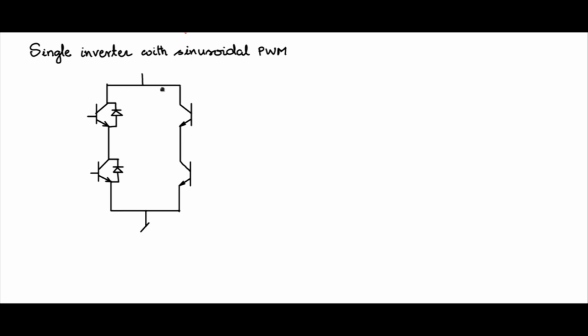So you also put another arm just like this arm. So you have another set of BJTs, a top BJT and a bottom switch, in this fashion. This is VCC, this is ground. So let us call this Q1, we'll call this Q2, this is Q3, this is Q4. And in between here we will have the load. So we will have an RL load, let us say L and R. So this is our full bridge converter.